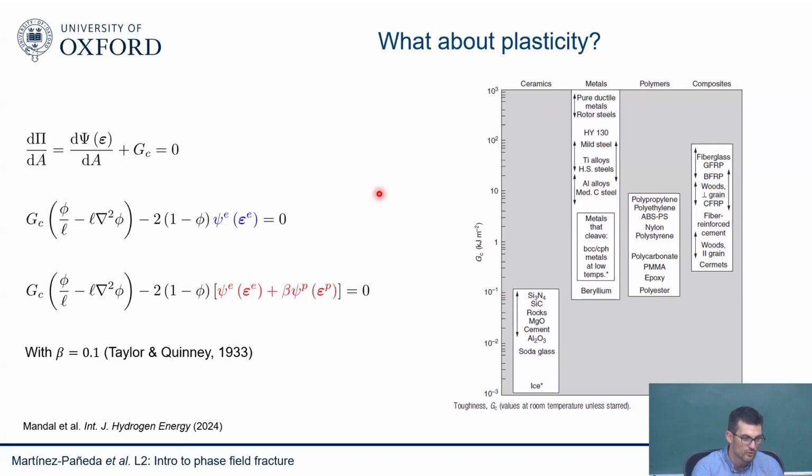That's true. So remember, the phase field is a competition, or fracture mechanics, a competition between a driving force, which is this G, or energy release rate, or strain energy density, versus a toughness, a material property, a material resistance to fracture. So okay, you just make the material resistance to fracture a bit bigger. What about the driving force? So you change something on the driving force.